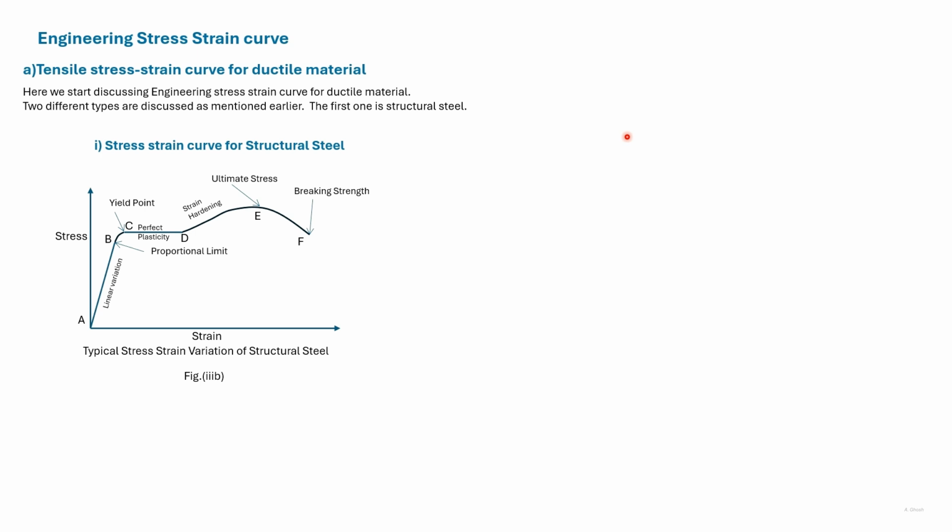We earlier mentioned that there's a reduction in the lateral cross-section as loads are increased. This reduction is quite pronounced in the plastic stage. However, after the ultimate stress is reached, a specific localized area undergoes reduction in cross-section.